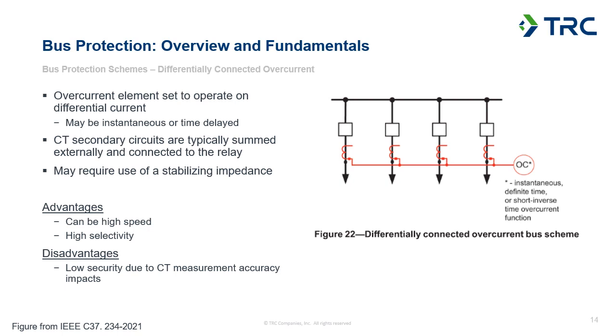And the overcurrent relay is basically just measuring that differential current. So assuming everything's ideal during normal load or external faults, we've got 0 amps. When we have a bus fault, we jump from that 0 amps up to a higher quantity, which would be the full fault current that we'd expect to see for a fault at that location.